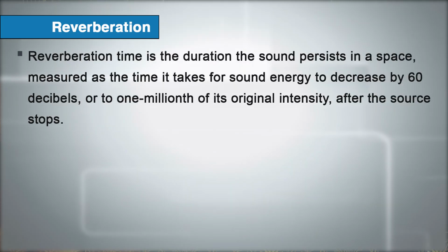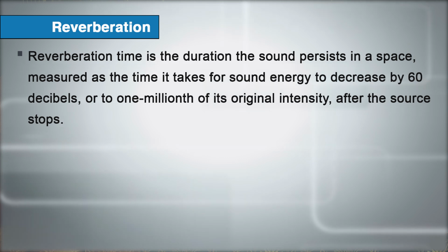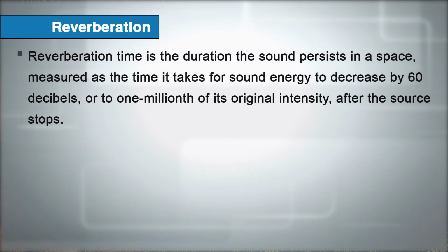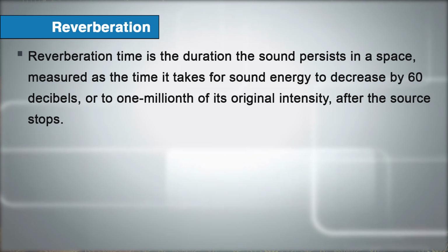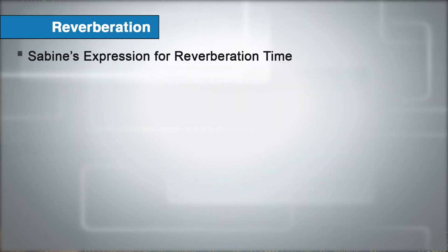Reverberation time is the duration the sound persists in a space, measured as the time it takes for sound energy to decrease by 60 decibels, or to 1/10 of its original intensity, after the source stops. Sabine's expression for reverberation time.